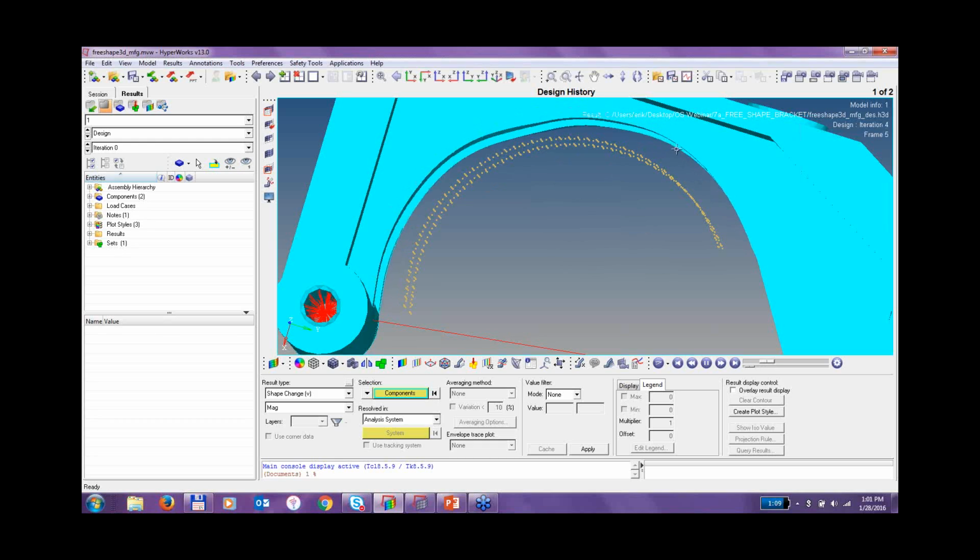Now, I would not have known that this area right here needs to bulge in, whereas this area over here doesn't necessarily. So morphing would have been near impossible for me to do. So the shape optimization wouldn't work well for me, whereas the free shape optimization, where I simply say these nodes on this face can move in or out and not pass this, that's what free shape does for me. So hopefully that explained that well.